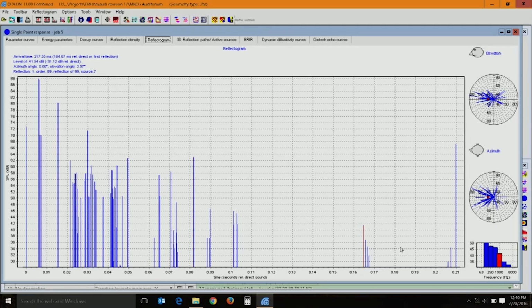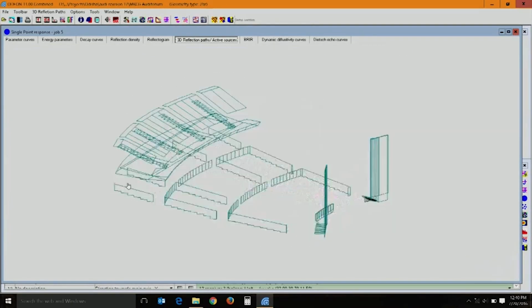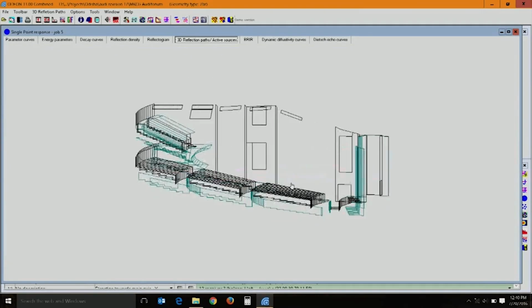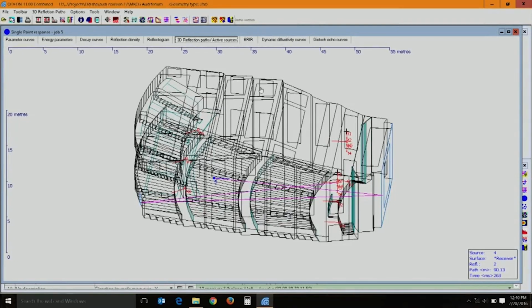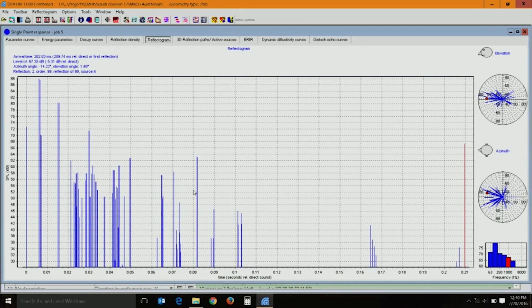You also find specific late reflections far off. They may not be very critical because in terms of sound pressure level they are pretty low. There is one more strong reflection here, at the end of it, very far in time. It may also appear that it strikes the rear wall. There are 2-3 more reflections happening across the hall. It may not be probable that it would hit all the way and come back. It is a judicious choice a person has to make between the surface it is reflecting from, the path in which it is travelling, and how intense the reflected sound itself is.